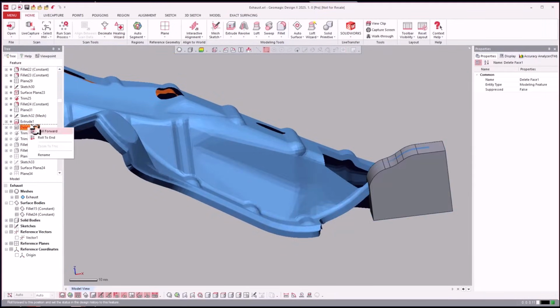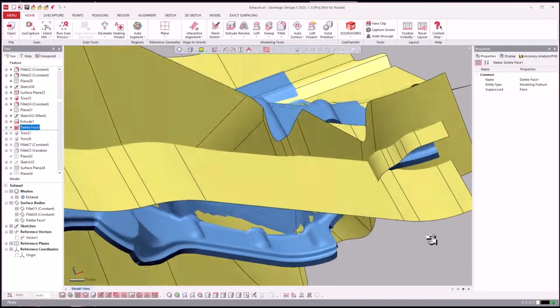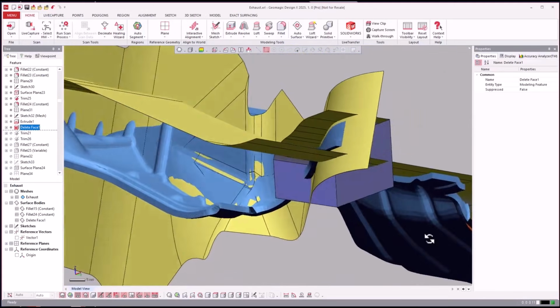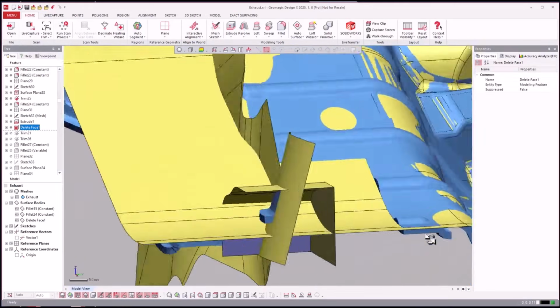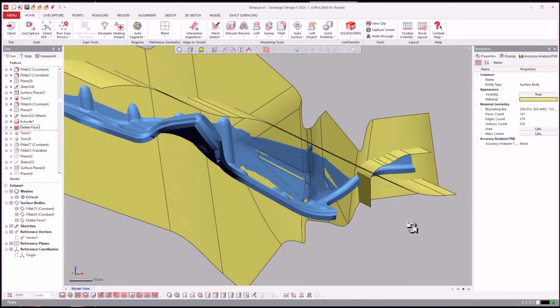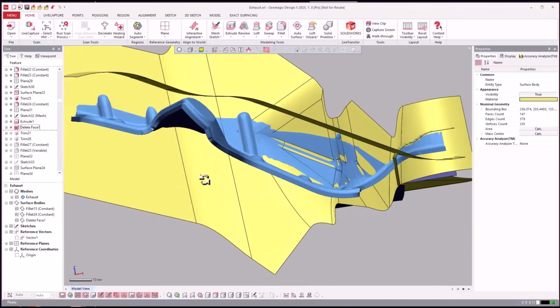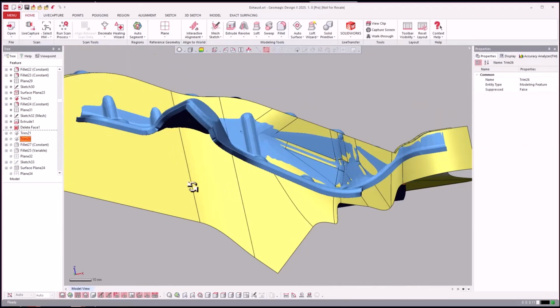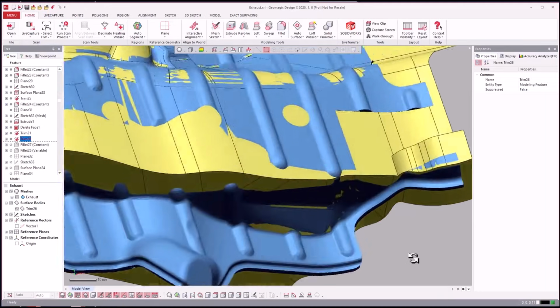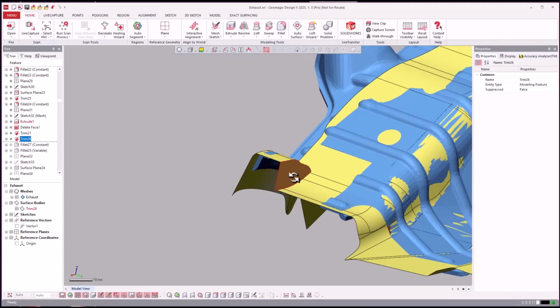We modeled it as a solid, deleted the faces, made it a surface. So you can do that too. That's another thing. Sometimes it's easier to do something like that. I'm not sure exactly in this instance why they did that, because they could have just extruded it as a surface, but they modeled it as a solid and deleted a face to make it a surface. So now, trimming that together. Maybe they wanted this to exist already without having to model in a couple different steps.